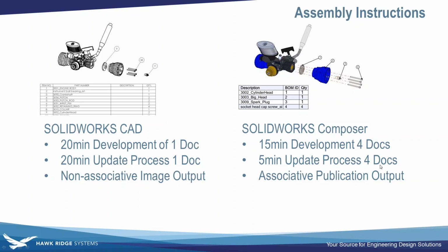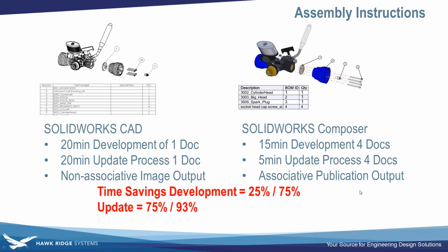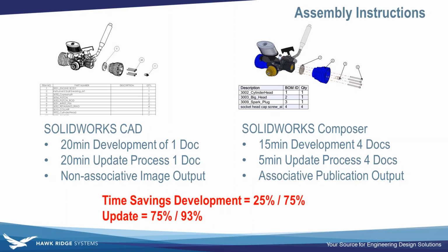But if you take into consideration that you're going to update from SOLIDWORKS and update 4 different docs, it's going to take about 5 minutes because you have to export those images. You have to re-export the PDF and the video, which is a pretty quick process. But sure, let's say 5 minutes there. But everything is associative, and that's really the point here: when you do anything in Composer, you don't have to redo it. When you update SOLIDWORKS, even if you add new parts into the SOLIDWORKS assembly and you jump into Composer and update it, those new parts are going to come in, you reposition them, and it's a real quick process, and you don't have to redo what you're working on.